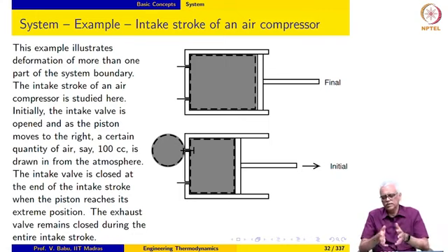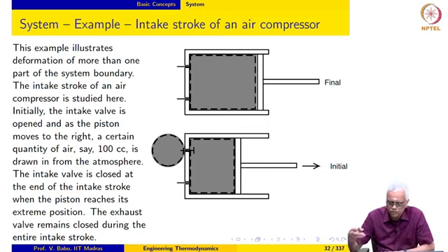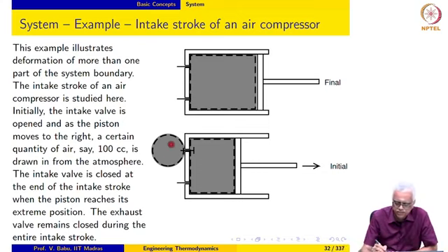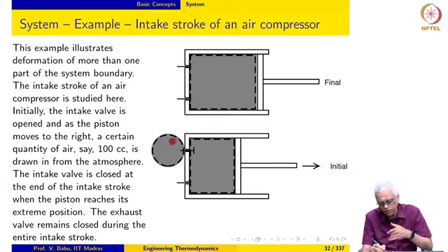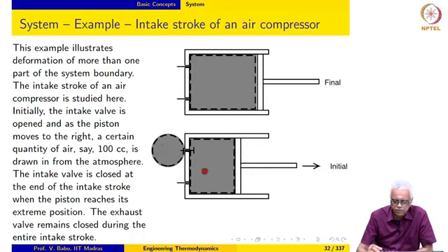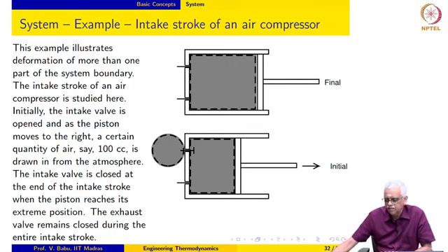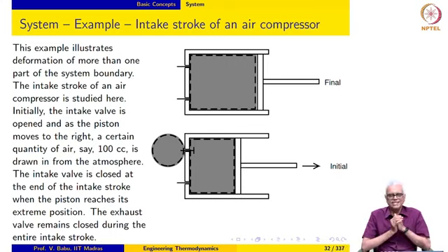And when we actually calculate the displacement work for a system like this, it nicely comes out to be the algebraic sum of all the work interactions. So, basically, when it shrinks the work interaction is of a certain sign, the surroundings are doing work; here the system is doing work on the surroundings. So, when we develop an expression for displacement work, it very nicely gives us the algebraic sum of all these work interactions with the appropriate magnitude and sense.